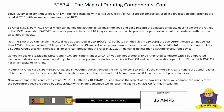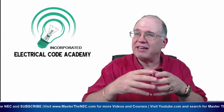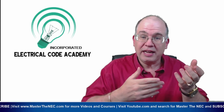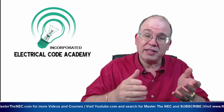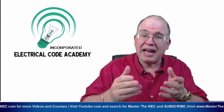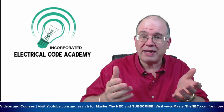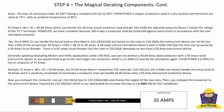In this case, the overcurrent device is the one that's going to be the ruling factor here, and it's going to require it to be a 6 gauge because I have to terminate that conductor on an overcurrent device that is at least 125% of the continuous load. And that's how we jumped it into a 6, okay? So an 8 was good until we started applying these adjustment and corrections, and then we had to deal with that, okay? All right, let's move on.